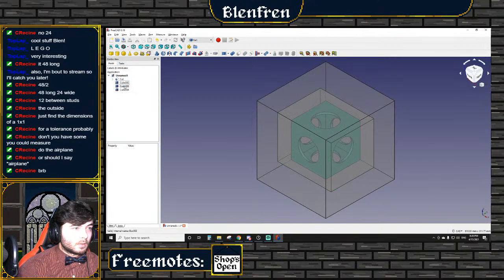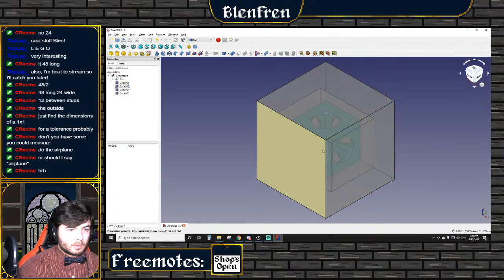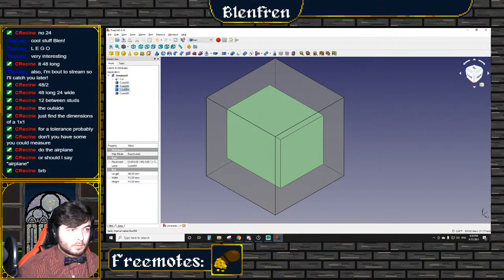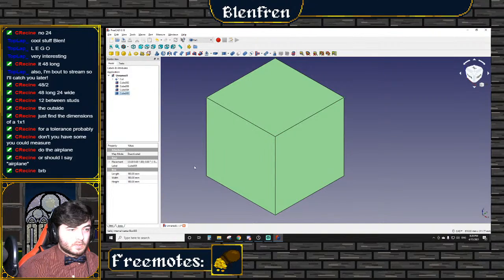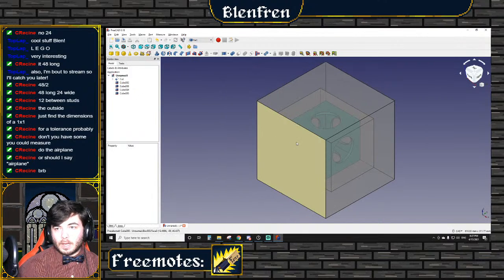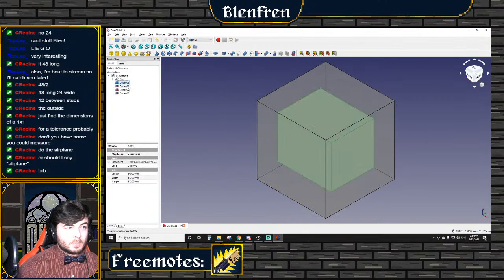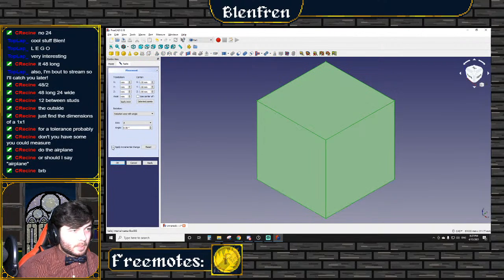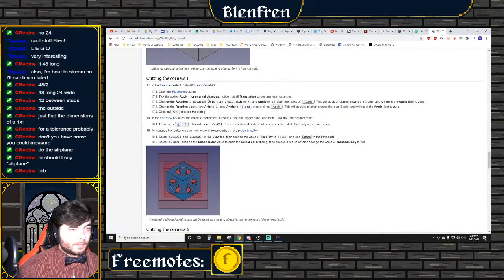Duplicate there, and they're also transparent. We're good to go. Everything's good to go. You can hit center, and cube 2 and cube 3 go into the placement dialog. Apply incremental change. It's set to 0. Notice that all translation values are set to 0.